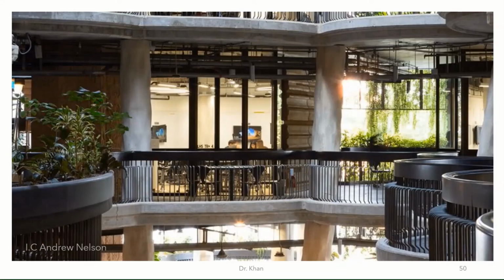The feature that I like the most about the Hive is the garden balconies. It looks amazing when the weather in Singapore is really very good. And I think one reason why the temperature inside the building is really very cool is not only the convection cooling system, but also the plantation and the garden balconies they have throughout the building from top to bottom. So there are two advantages of vertical farming. Through respiration, it keeps the temperature inside the building really cool, and it also helps absorb carbon dioxide through the process of photosynthesis, as we all know. So it's a way to reduce carbon emissions and at the very same time reduce the energy requirement of the building.